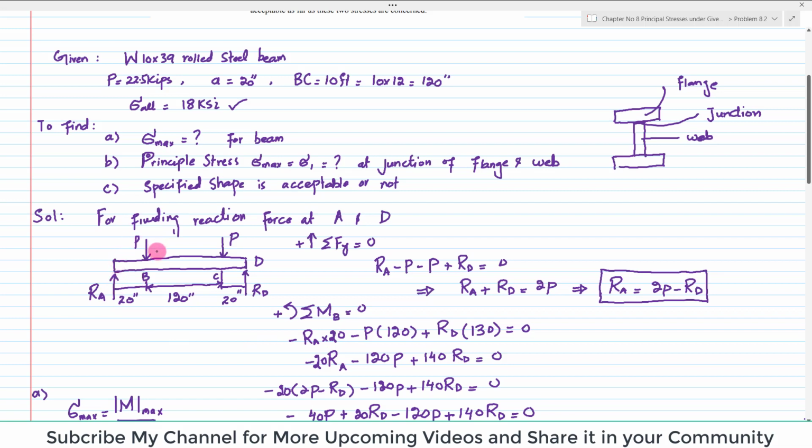A negative sign shows that clockwise rotation is negative, so minus 20 RA. Similarly, another force which is producing moment is P into the perpendicular distance 120, and it is also producing clockwise moment. So this is again minus 120 P in the clockwise direction. The other force which is producing moment about point B is RD, so RD into the perpendicular distance, which is 140. Clear? So 140 RD is equal to 0.